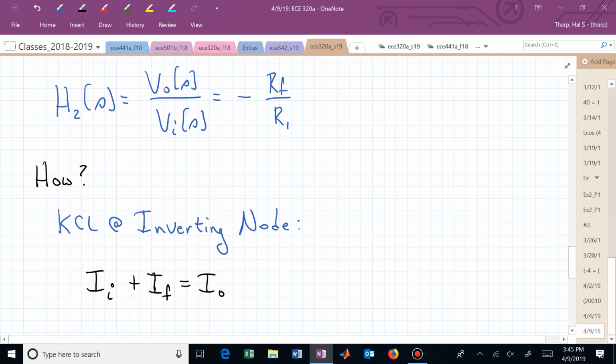That's what we have. And you just said because of the high impedance at the inverting terminal, we can say that there's no current going into that op-amp circuit, and now the sum of those two currents at that node have to sum to 0.